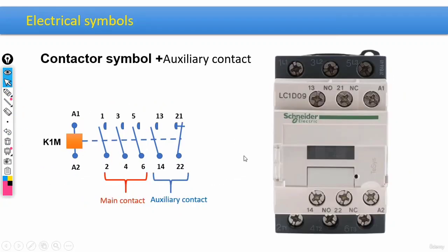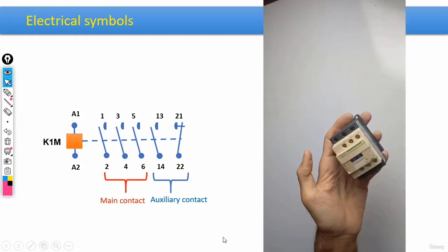Now guys, if you remember, we said that we might have auxiliary contacts in our system as well. Now, if this was the case, this is how we would display them. Again, we have the power contacts right here, and these would be the auxiliary contacts, which, as I mentioned a few minutes ago, we would usually find in control circuits. Now, just like what we did in our previous session, let's watch a clip to understand everything better.